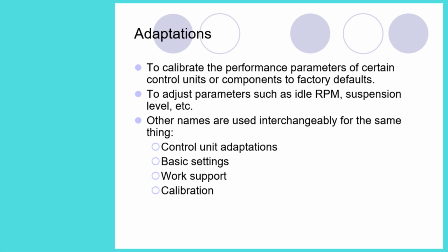The most common example is the throttle body on drive-by-wire VW vehicles. If the throttle body is removed during servicing, the throttle flap may move during the process. When it is replaced, the system may think that the flap is at 0 degrees, when it may actually have moved to 5 degrees. This may result in idling or fueling issues. Throttle body adaptation would recalibrate the system and ensure that the throttle flap is set at 0 and matched to the system.